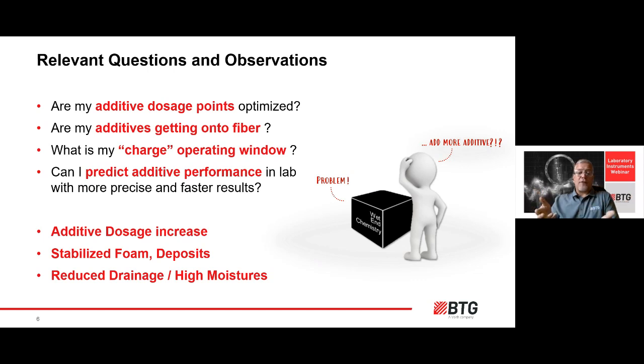The bottom 3, if you're experiencing these things, these are things you might see every day. You're in your morning meeting and people are talking about increase in dosages, dealing with foam or deposits, outbreaks, stickies, etc., issues with drainage, having failed release from formers, having high moistures. If those things are going on, it's quite possible your process is telling you you might need a little more information in this area. So if any of these things resonate with you, you're in luck. We're going to spend the next few minutes talking about how to get more information that can answer some of these questions and certainly address the things that are seen on the bottom that are almost certainly costing you in production and dollars.